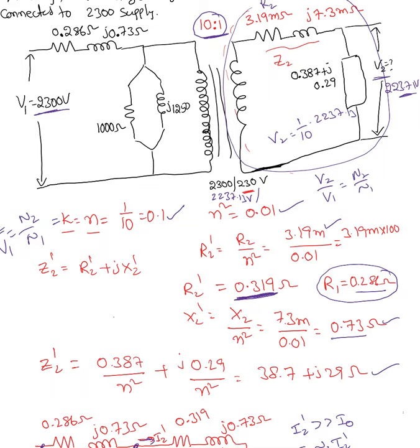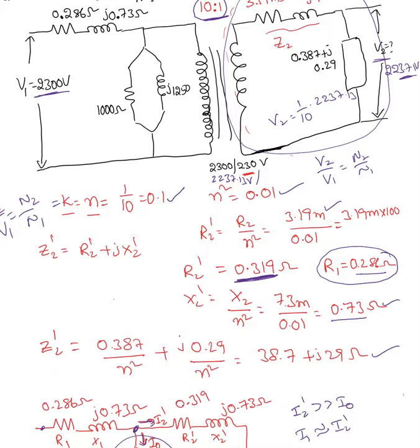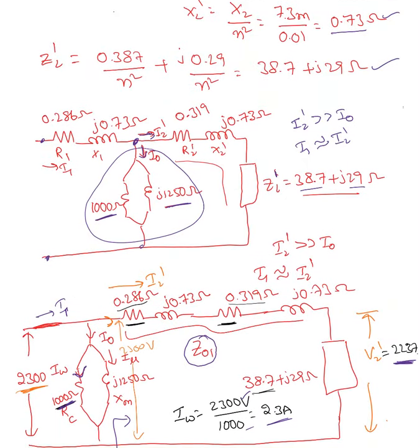Is it good for our equipment? Probably okay. Most equipment is designed so that even though it says 120 volts, it can probably work between 110 and 130. But at the same time, it's not recommended to operate your equipment beyond that range. If the voltage is further away from 120, it's not recommended to use that equipment with the lower or higher voltage.